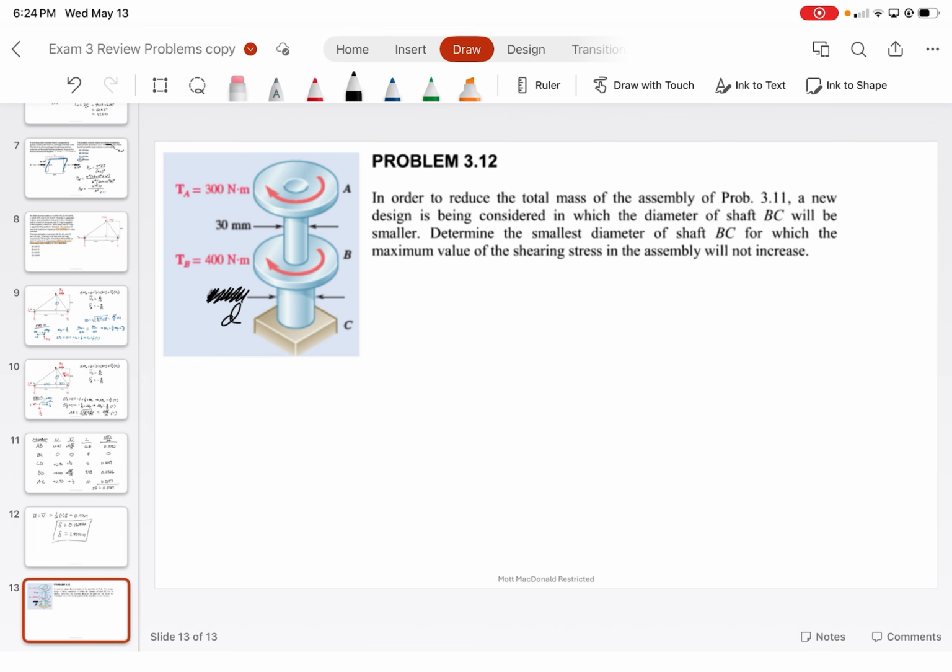Technically, the first problem we did was kind of doing it two different ways, because we did strain energy to obtain the deflections, which you can fact check using those standardized tables. If you just use the standardized tables that I provide you on the exam, it's just a matter of applying compatibility at that point, and it avoids having to do all of those first steps.